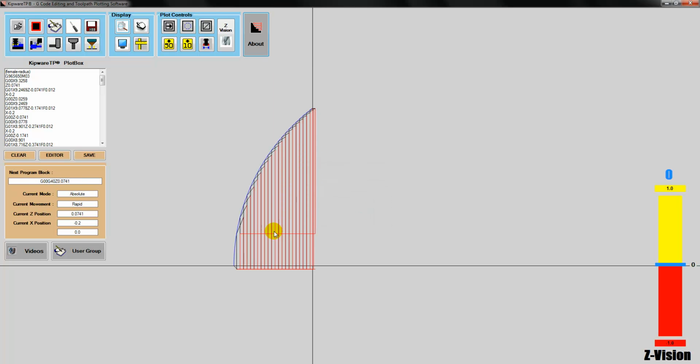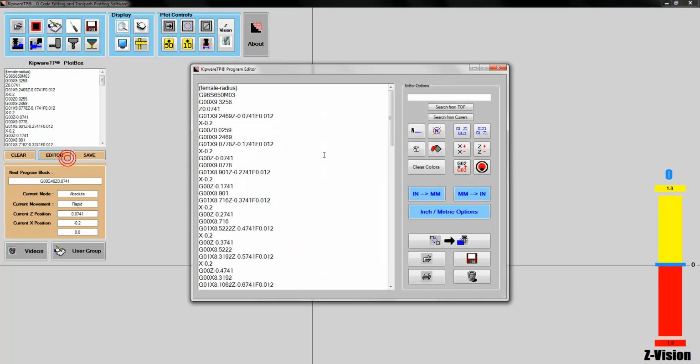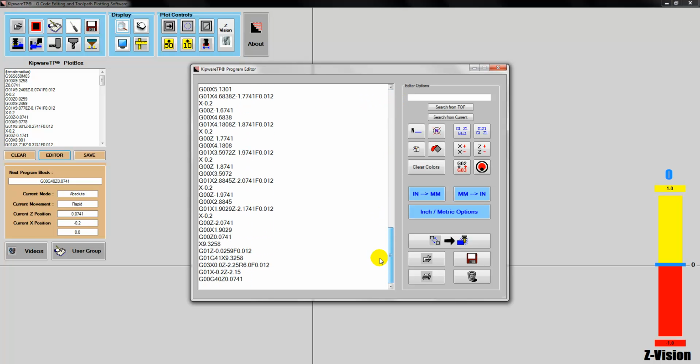It's roughing with a facing type of format to rough out the material, then coming through and doing a profile cut of the radius of the part. If we take a look at the format of the program, you can see it's a standard FANUC format, X and Z's. They have decimal points. The last line here, which does the profile for the ID radius, actually uses an R designation. And again, his machine uses an I and K.